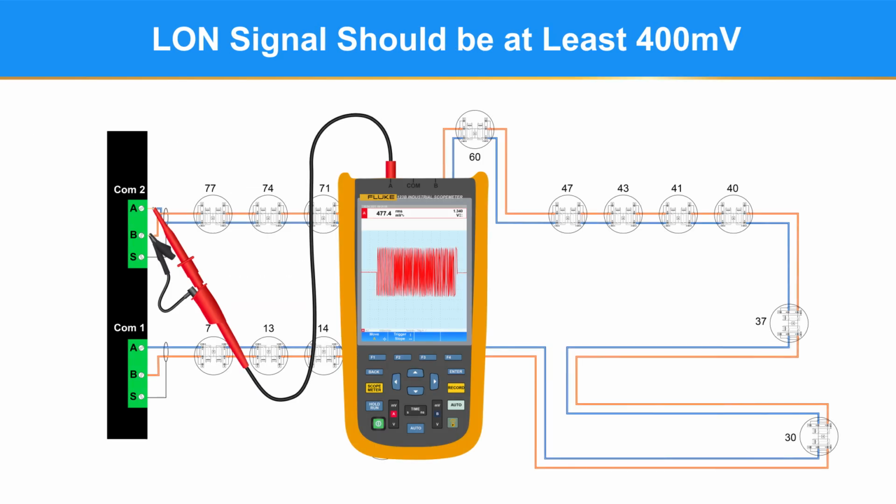It is difficult to see if attenuation is the cause of the loss of the heartbeat without specialized equipment like an oscilloscope. If you do have an oscilloscope, you need to verify the communication signals are at least 400 millivolts in amplitude. If the signal is above 400 millivolts at each controller COM port, attenuation is not your problem. If it is below 400 millivolts, you need to find out whether it is due to network engineering or excessive